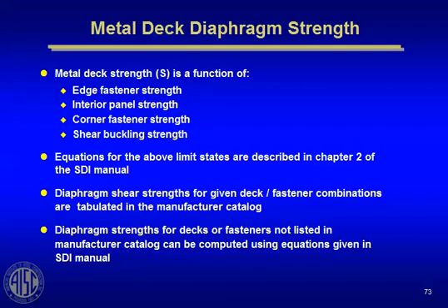You can't really carry much more than 1,200 pounds per foot of shear in any metal deck without strengthening the deck. There are fillers that you can put in the deck that increase their capacity that they use out in California for high seismic zones, but generally most metal decks have 400, 500 pounds per running foot of shear capacity in their normal state.